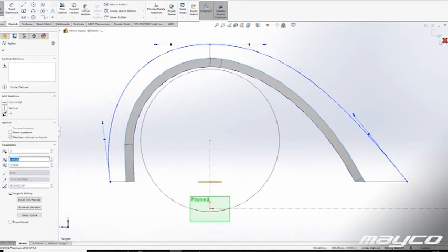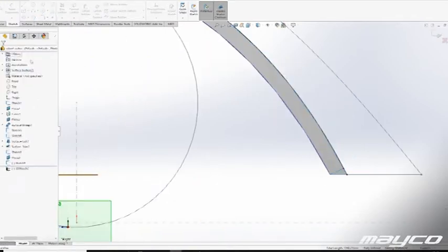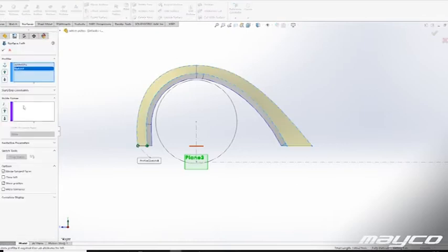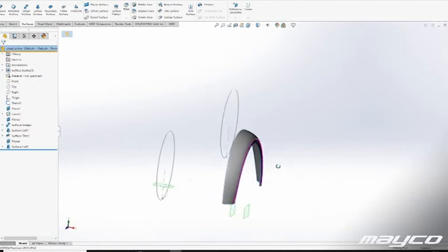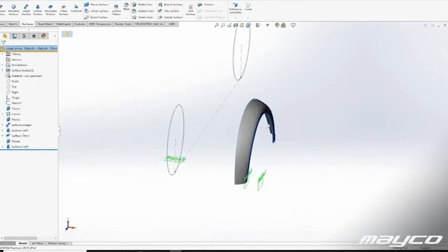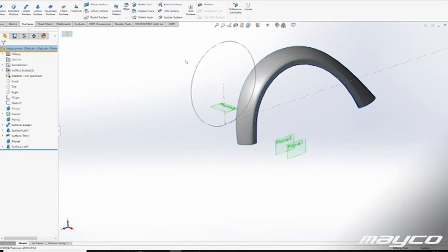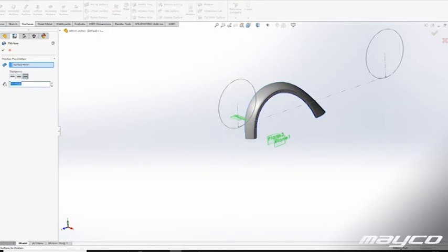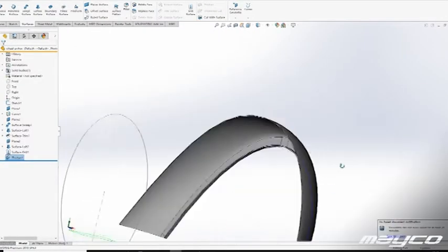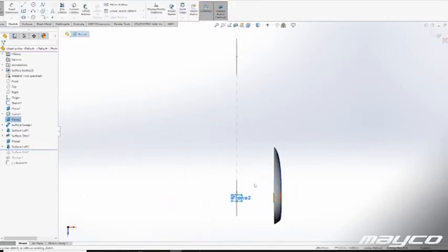What that means is that if you look at a front plane, it might appear that you go through a sketch line. However, if you then rotate your view, where you look a little bit 3D from the front, you might see that you're completely missing the line that you thought you were hitting, and therefore you use the tool pierce. If you do that, then all the lines are connected, and you can use the sketch lines for the shape and the guidelines to make your shape that you want.